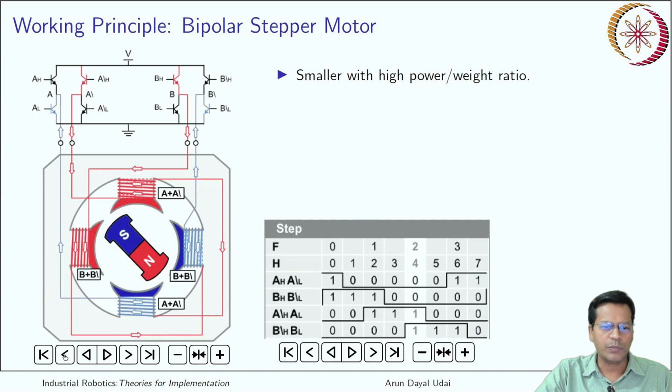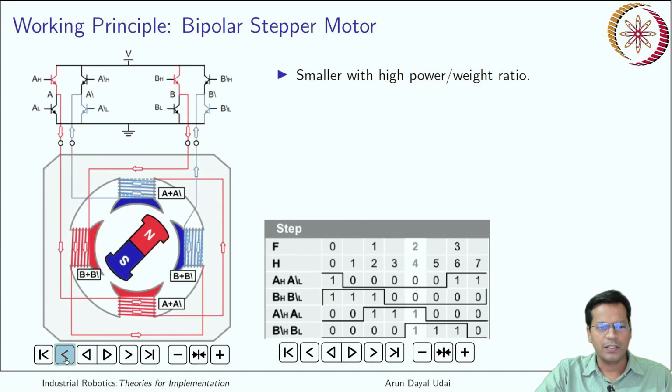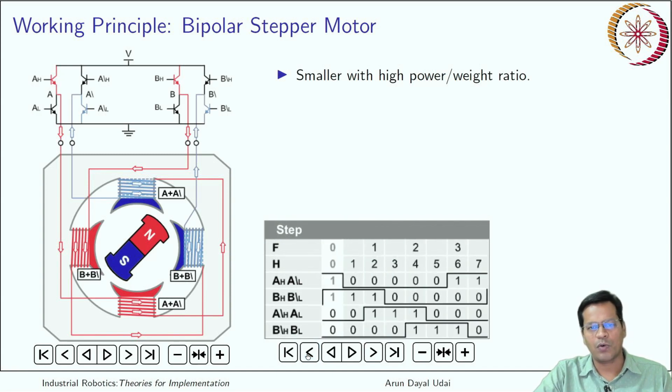You just do something very reverse. So it rotates in a counterclockwise manner. So doing this can make it go this way. Okay, so doing this will make it go in the opposite manner. Same here. If it is moving like this, you just have to reverse the sequence of the pulse that goes to the coil. So that way you can reverse the direction.